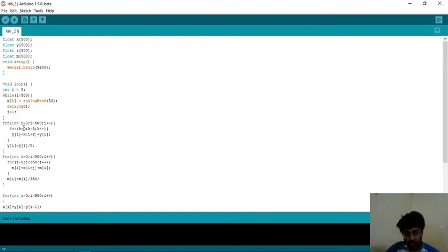The moving average filter works as an averaging of the previous values with the present value. I mean, we take the average of the last previous eight values along with the present value to give the output. So we are taking the averaging as eight samples, and we get the moving average filter output as y.